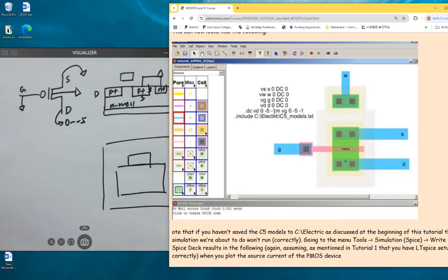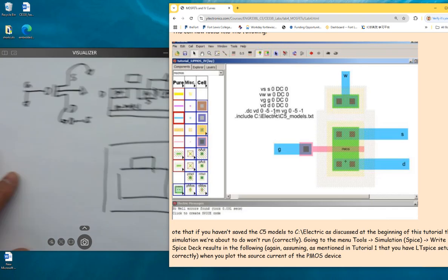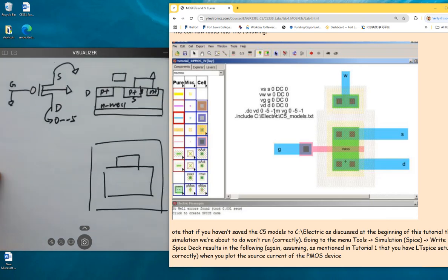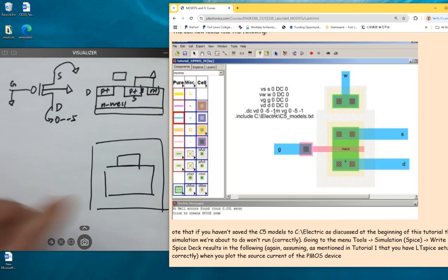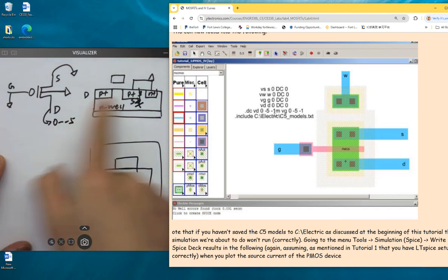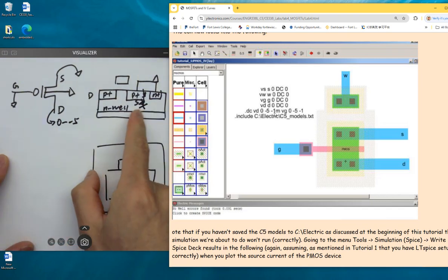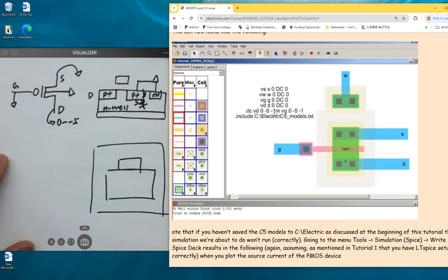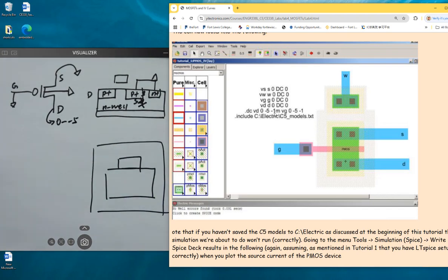So remember when we are talking about PMOS, we would like to short the N-tap here to the highest potential of the circuit. Does it still apply to this principle here or no? Is it confusing? Too much information? But it's very important, okay?